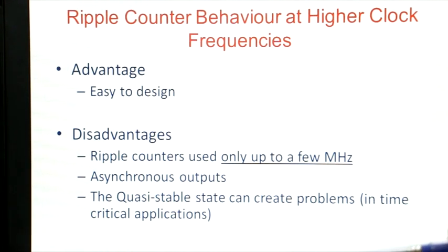Mind you, in this particular experiment we use 74S112. That's why it is so small, that instant for which it is high, that state 110, which you are able to see on the scope, is extremely small. But however it's there. If you had used a slower gate like a standard 7400 TTL or even an LS TTL, you would have seen that quasi-stable state more clearly.